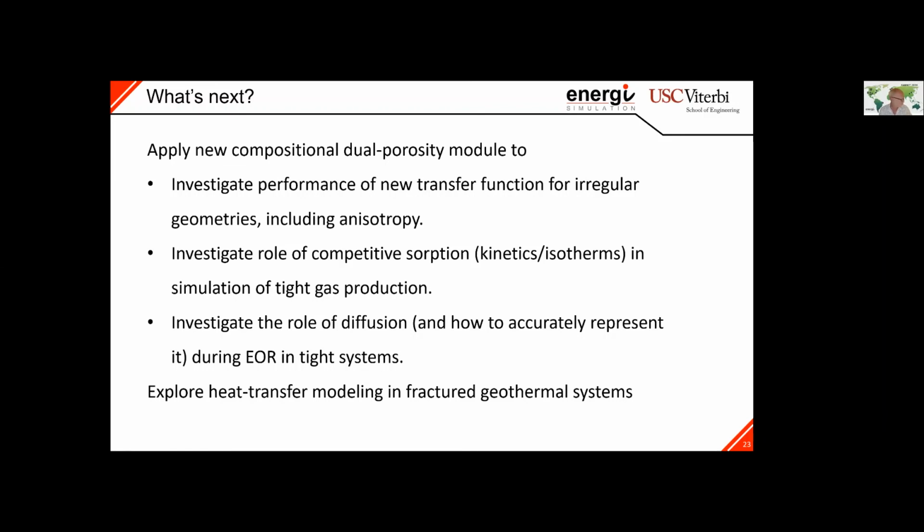Let me wrap up with a few words on what's next. Since we now have this new capability of dual porosity compositional modeling, we will move forward and investigate performance of new transfer functions for irregular geometries, including geometry, anisotropy, etc. Integrate and investigate the role of competitive sorption when we are looking at tight gas production, and also implement and investigate the role of diffusion during EOR and tight operating systems.